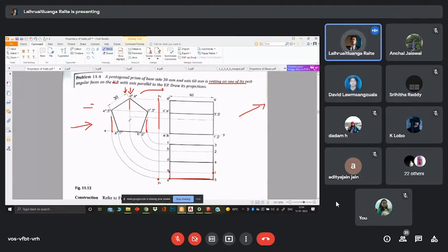For D4, it goes on like this. We get a point over here and here, and finally we get D4. And D4 is a solid line because we look from the top and it is the line that comes closest to us. Same goes for E5 and C3. They are still visible. All right, so it goes on like this. So when a solid is parallel to both the horizontal plane and the vertical plane, we have a profile plane, and our projection will look like this.